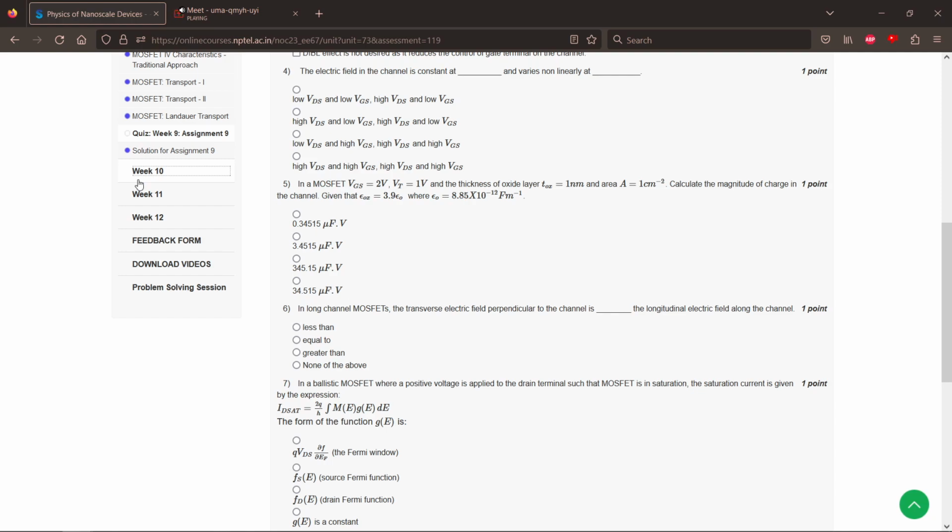Even when the barrier potential may not be sufficient, some electrons will tunnel through. So there will be a baseline tunnel current, a kind of background current. Quantum mechanical effects will start manifesting in that form. But for our present analysis, we are staying away from that, because we are not going to the absolute cutting edge. What we are looking at is the general short channel devices, which is actually up to the point of FinFET technologies.